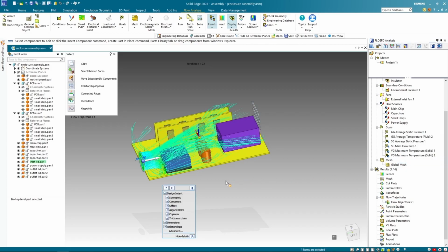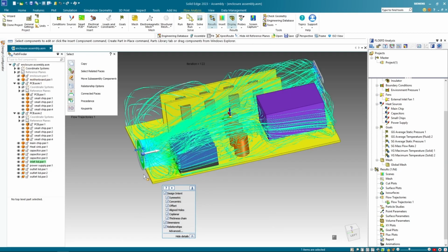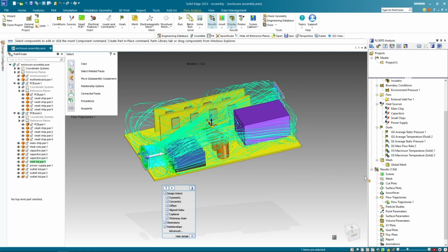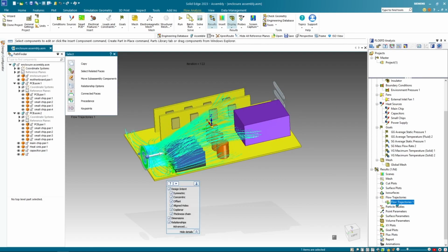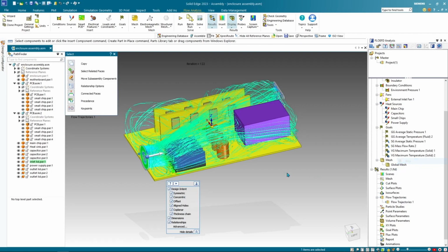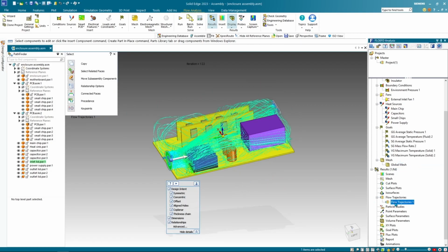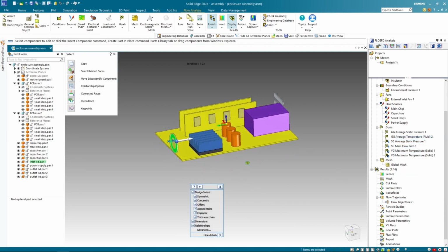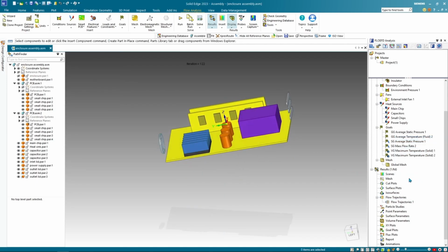You can hit play to check how exactly this whole trajectory or the flow is going to look like from start to the end. Next, we can check for some cut plots here. So let me go ahead and hide this first result. And next, we can go and check for the cut plot. So say insert cut plot, and let's use the XY plane here as a plane to check the cut plot.